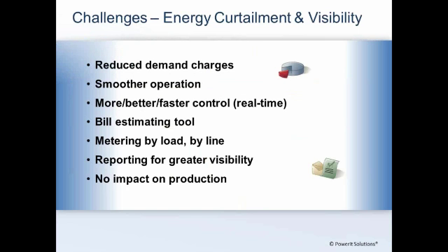So we went in early on and put in a very minimalistic demand control system that would count the pulses and would turn on a light in the facility, and that light would signal the furnace operators that they needed to turn down their power. We found it to be very ineffective. We stepped in with the advent of PLCs back in the early 80s to where we were able to put in a demand limiting program where we connected to the furnaces, and as we reached set points, we would start to reduce the power within the facility.